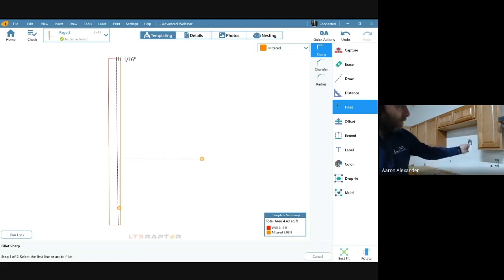Right now we could tape that up to the flush panel at the bottom down here, tape it up down there, shoot both the lines, offset it up that 1/2 inch. Now we totally took care of our laser stretch. No laser stretch, direct shots, very accurate to get rid of that stretch there and using that target to do that with. Okay. So new awesome little target deal here for helping you guys out with the backsplash, not getting any stretch there. All right.